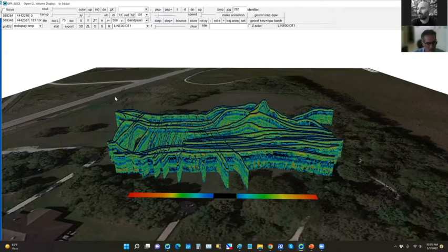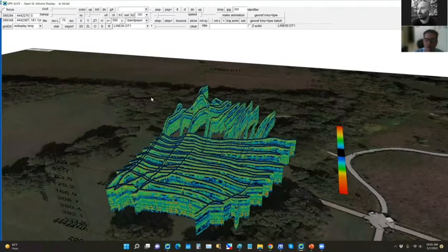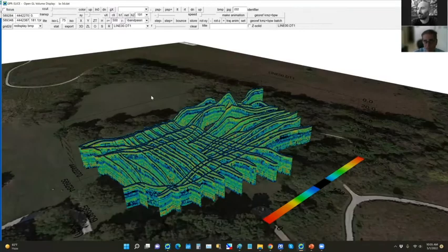Okay, in terms of topographic adjustments, those are the three ways to do it. You can draw topography, you could import a digital elevation model on a local grid, or you can even import a digital elevation model on a GPS grid, or you can use the GPS information.